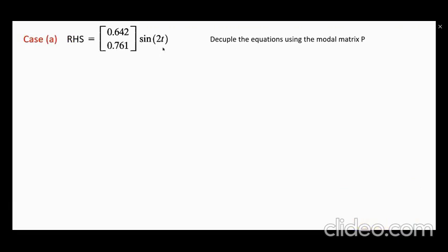Now, let's look at the first case. So the load has this frequency 2, which is neither one of those natural frequencies, incidentally, and it has a load vector which looks like that. So let's actually go ahead and diagonalize the stuff. So here is the problem, and for convenience, notice that I'm not taking any damping. Obviously, even if you had damping, the concept of resonance is independent of that. It's just convenience. So I need to diagonalize this.